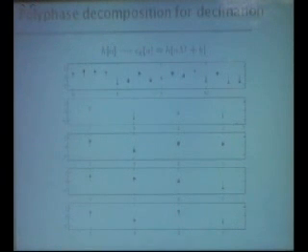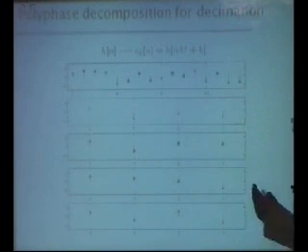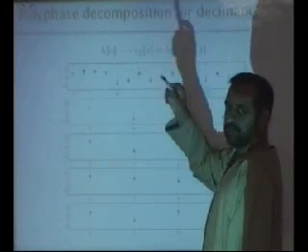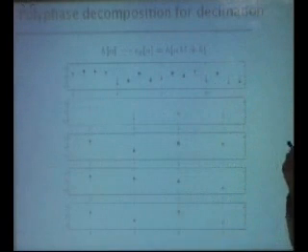And this is the polyphase architecture. It says that if you want to do this, and we'll find a mathematical reasoning for it, primarily you design a low pass filter. As I showed you in MATLAB, you say FIR1 with cutoff pi over M.